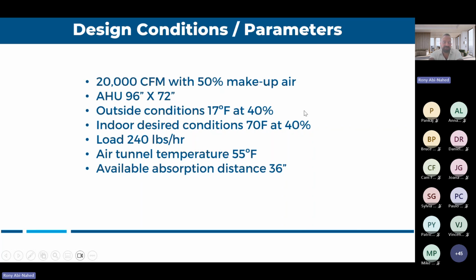pounds per hour. Because if you have a 20 pound per hour job, it's not bad to insulate. You always have an advantage, but the saving you're going to make on energy will not cover the cost you're paying extra for the insulation as a first cost. To be honest, usually below 100 pounds per hour, the energy you're wasting is not that big because you don't have enough steam running to lose that much energy. So to justify the cost of adding insulation versus the cost of saving on energy, it's not worth it. But any job higher than 100 pounds, that's where it starts making sense.